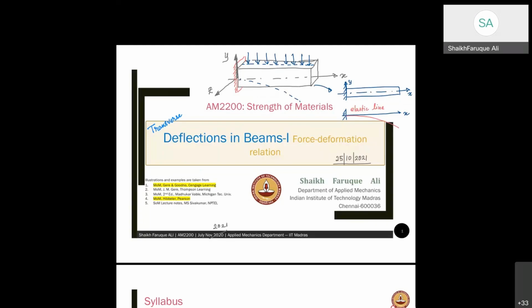Okay, we don't completely draw the full beam and show its deformation, because the deformation in the top layers and the bottom layers will not be same as the neutral axis layer, because they will have compression and tension, and this compression and tension will increase their length or decrease their length, whereas neutral axis will remain same in length, and therefore we look at the deformation of the neutral axis only, right? So that's the important thing that you need to know.